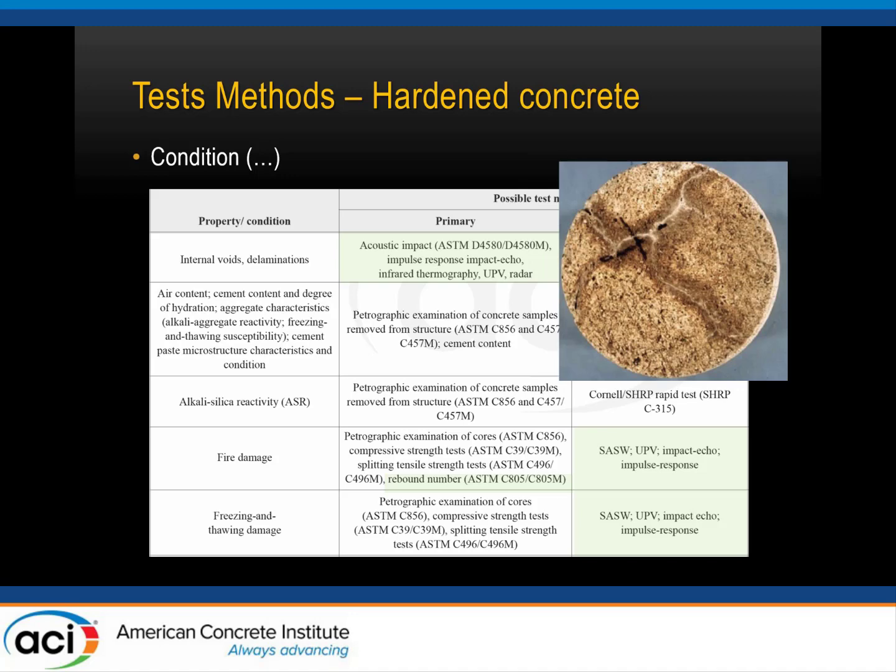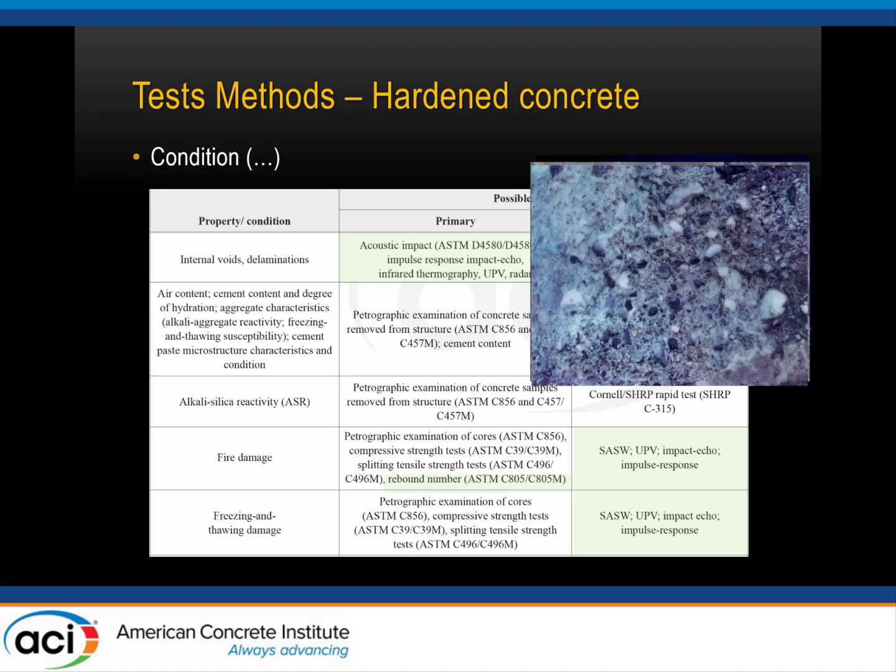Like, for instance, this is an example of ASR problem in concrete. You've got your freeze-thaw damage in concrete. So in order to really confirm these types of problems in concrete and to point the finger on the right cause, petrographic examination is typically the final ultimate tool in order to cap the analysis.